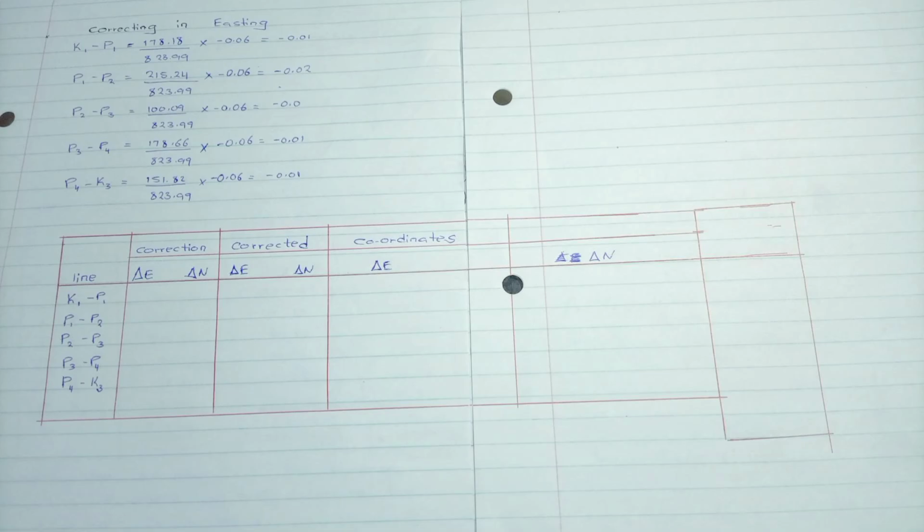So having completed the drawings, we'll start inputting all the values from the previous calculations for the correction in easting and for the correction in northing. So we'll just copy what we have calculated from our previous, from K1 to K3. Then all the values that we have from K1 to K3, the small corrections will come and will correct the values that we had on our previous table. We will minus and add according to what the values entail.